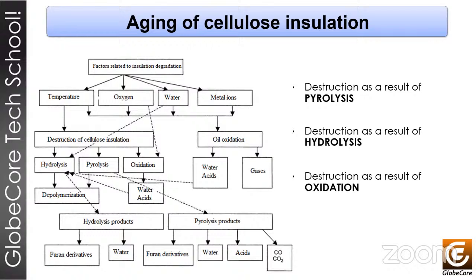The degree of degradation of solid insulation of transformer winding is determined by the degree of polymerization, that is, durability. However, its determination requires taking insulation samples from the most heated parts of the winding and involves opening the tanks, which, as a rule, is undesirable, and in operation is generally unrealistic.